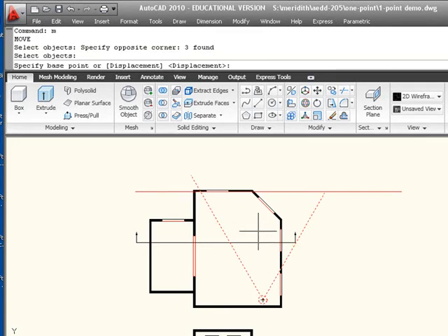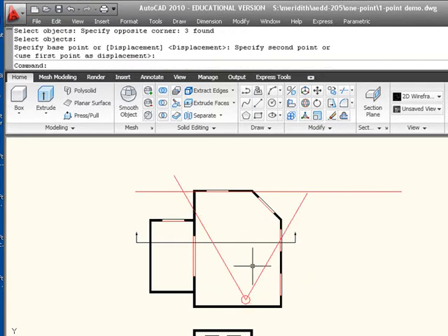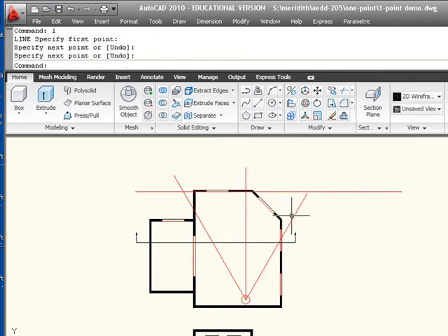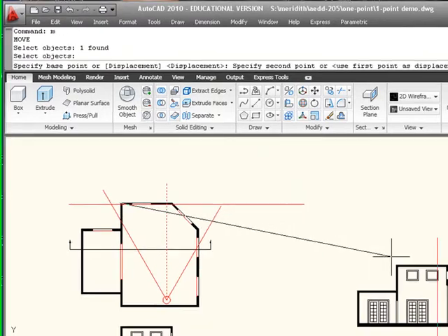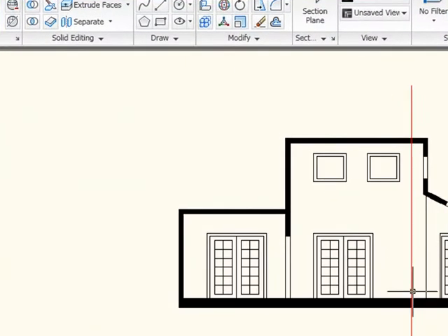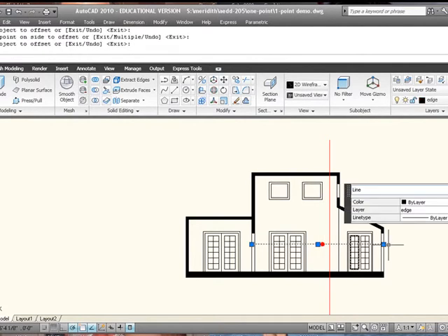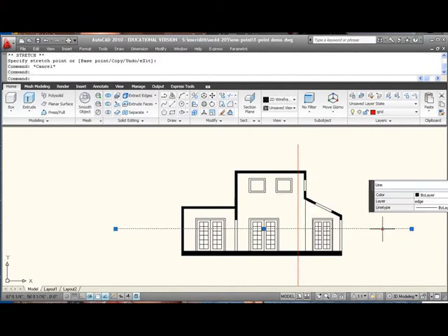I'm going to put myself just a little bit off center so that my center of vision, draw that line in there, is right about there. Okay, so that puts that same point so that that center of vision is right about here in this elevation. So that means that's putting us standing right here. The height of this person, this is the floor line right here, will be around 5 feet. Let's put ourselves at 5 feet this time. And this becomes our horizon line. So let's put that on the horizon line layer.